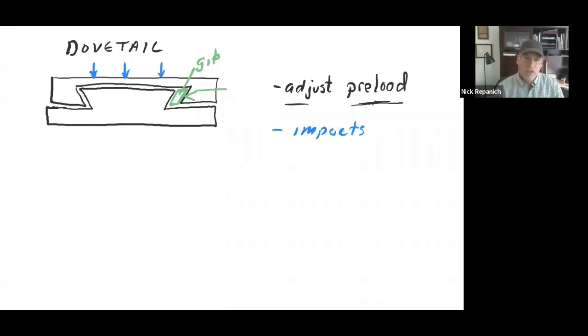And they use steel with the bearings because the ball bearings, the housings, this plate, all change at exactly the same rate. So that's why the first thing I said was temperature changes. You could change the preloading with temperature, but that's not a very predictable thing to do.